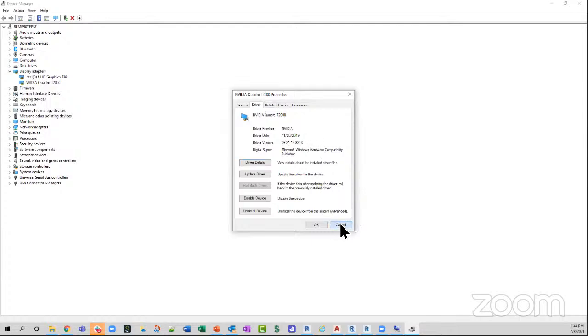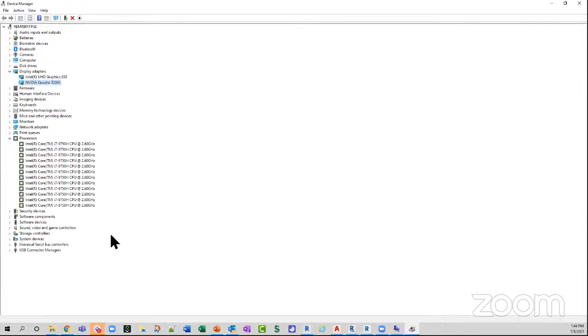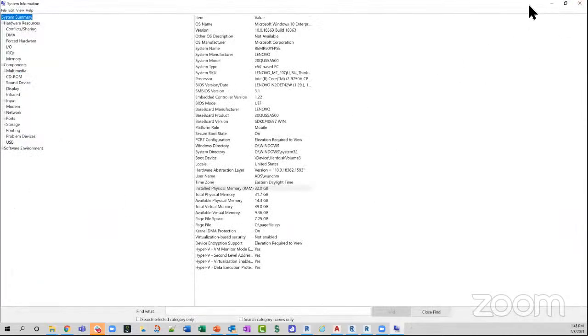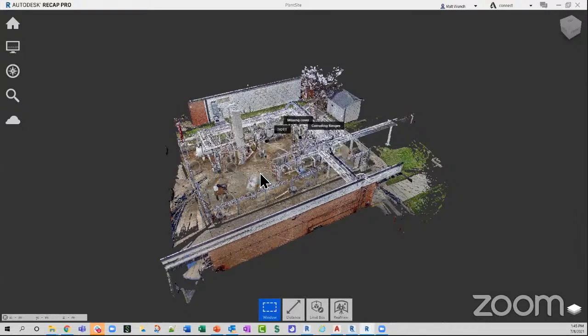Sometimes in support, I do see a really good machine, like 128 gig of RAM. You would think ReCap might run twice as fast with 128 gig of RAM. But I see once you get it beyond 64 gig, performance kind of stays consistent, because that's about as fast as ReCap will run. It's good info. Right on.